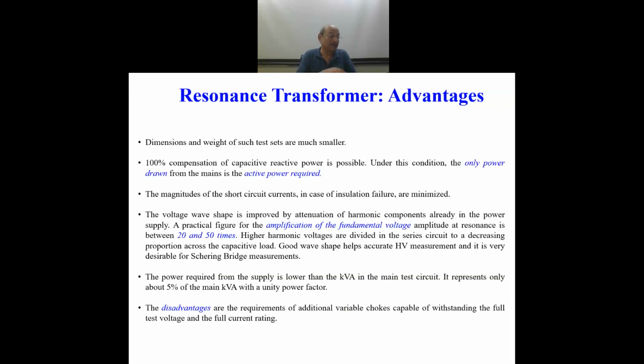When the frequency is increased, the capacitive reactance would go down, and the inductive reactance would increase, isn't it? XL is equal to omega L. XL will increase in direct proportion to the frequency, and the capacitive reactance, 1 upon omega C, is inversely proportional to the frequency. So you can equalize the XL and XC to the desired value.